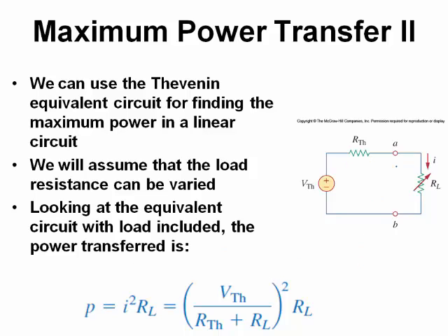So there is a point where the power will be optimized here. Just as a simple circuit analysis right here, you can find out the power in the load. So power in the load is I squared R load. If I do a little loop equation here, the current is the voltage divided by these two resistances, squared, times R load. So that's power in the load.